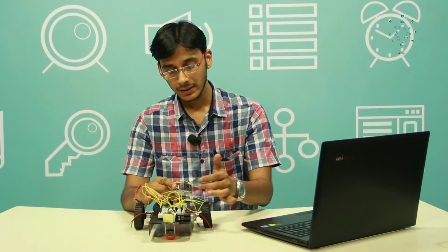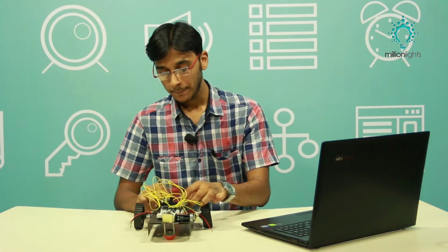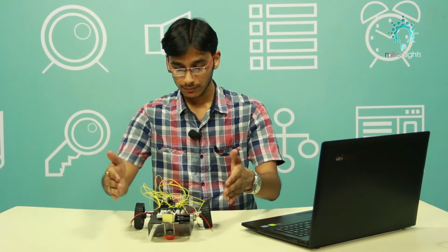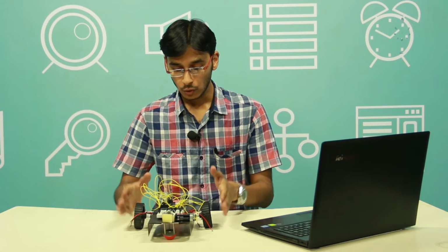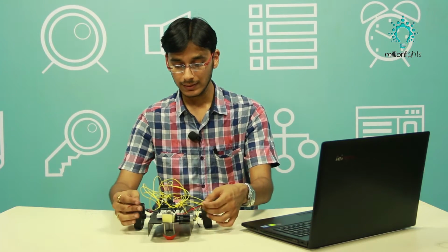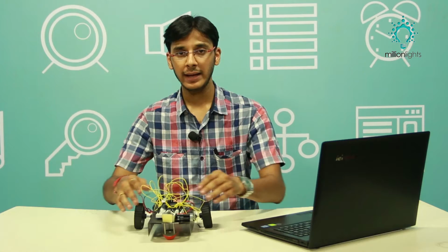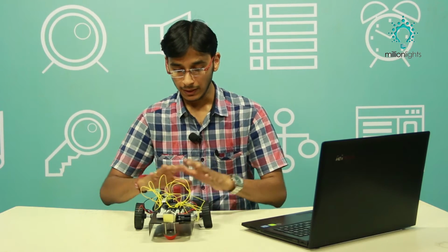So with the help of a connector I can directly plug into it, or else I can make a 5 volts power supply and give it to it. So we have to take care of these things also. I hope this is quite easy: place your hardware onto the chassis and connect. Just make sure that these 4 pins are connected at the appropriate places of the L293D, and I can control the motion of it and make it work according to my instructions.